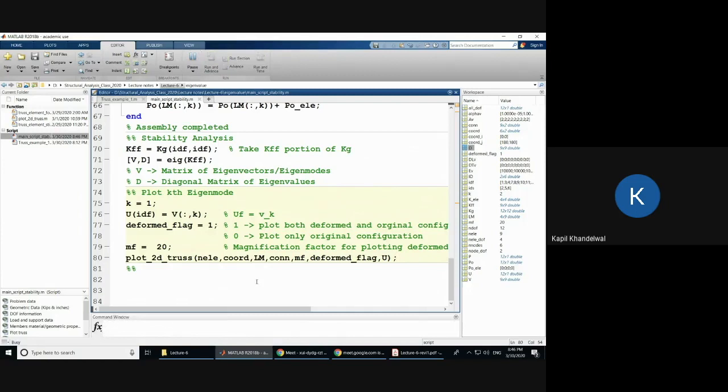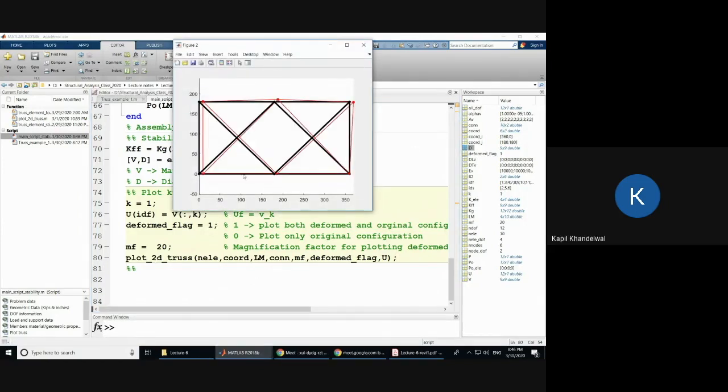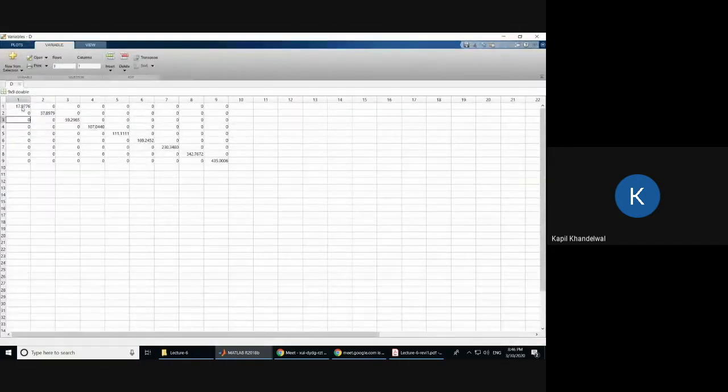And so this is the first eigenmode. And actually, this is a strain-inducing mode. And because it is associated, if I look at the eigenvalue, it is still positive. The first eigenvalue is positive. All the others are also positive. So the system is stable. And there is no eigenvalue that is 0, or less than 0. So we are good here.